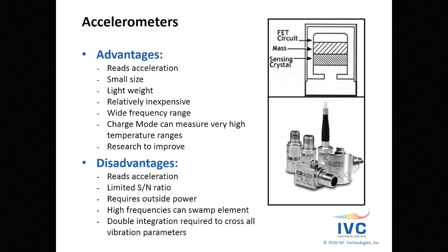Here I wanted to take a quick look at accelerometers and go over some of the advantages. They read acceleration. They're small in size, lightweight, fairly inexpensive. They cover a wide frequency range. Charge modes in particular can measure very high temperatures. And there's a lot of current research to improve the design. This is kind of the workhorse of vibration analysis.